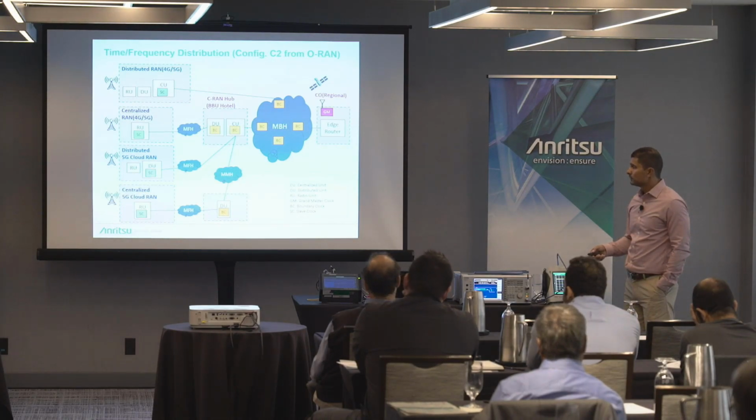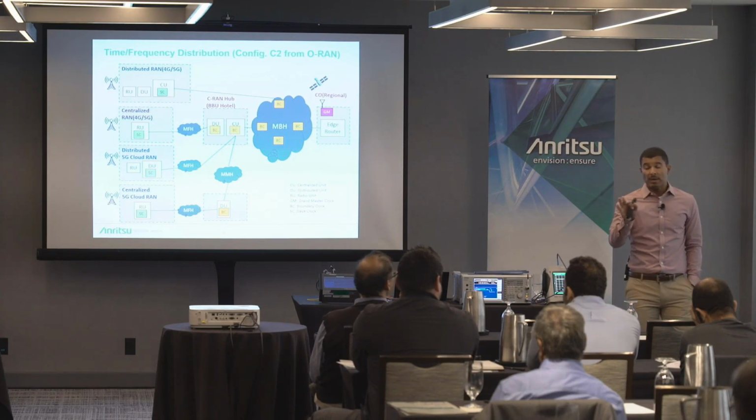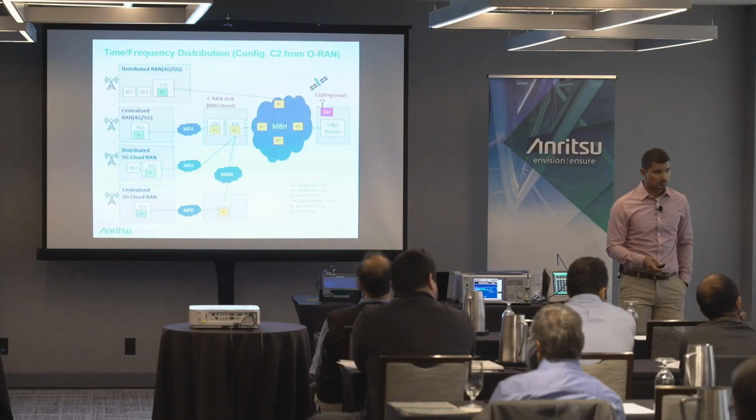Correct. So it won't matter if that one's farther from the grandmaster, as long as the shared boundary clock that they hit still falls within that time frame. Right. Or even if the boundary clocks aren't shared, as long as the boundary clocks are within that same time difference to the tower. Exactly. That is correct. The boundary clocks are getting accurate timing, they are retiming.